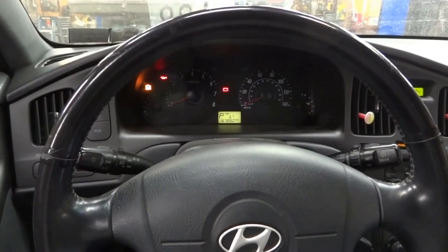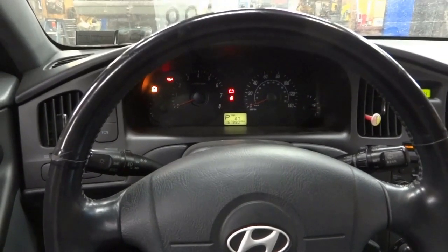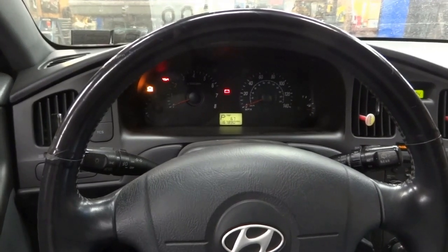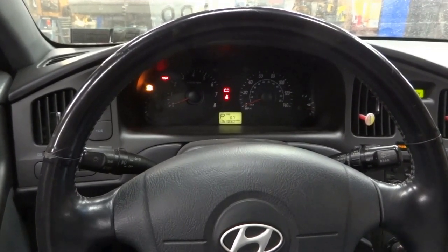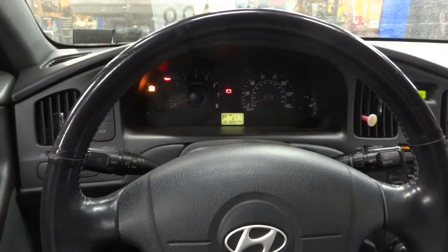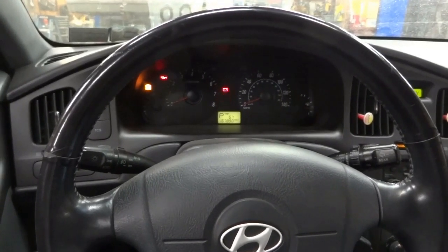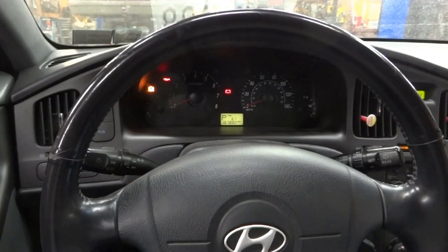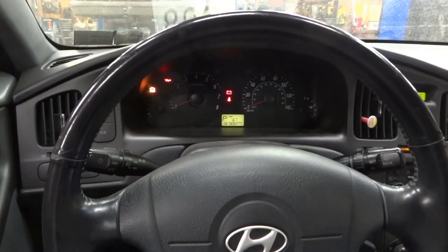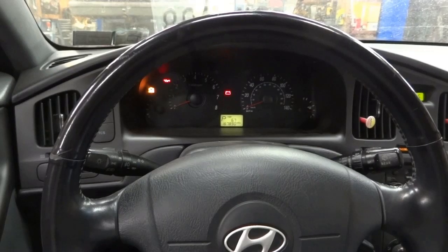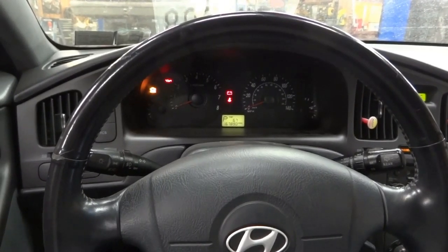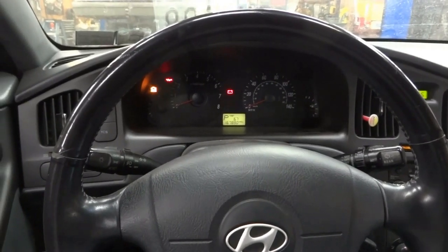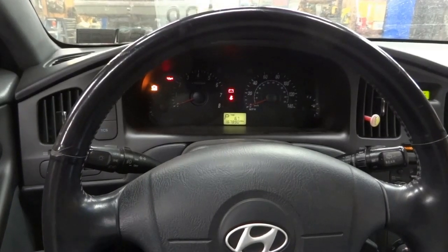What we're gonna do is go under the hood, and we can do it two ways. We can remove the O2 sensor and put a pressure gauge in the O2 sensor hole, and start the engine to see if we have high pressure in the exhaust system. The other test we could do is use a pressure transducer inside the cylinder to see if we have a restriction in the exhaust system. Actually, the other method is what I'm going to use. We're going to use an in-cylinder pressure transducer to see if we have a restriction in the exhaust system. Okay, now let's go under the hood and do that.